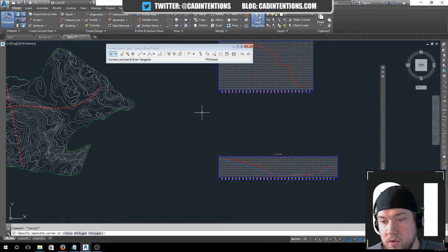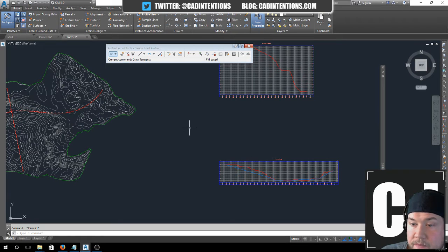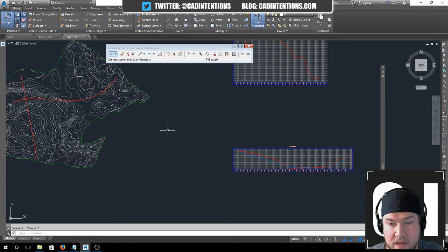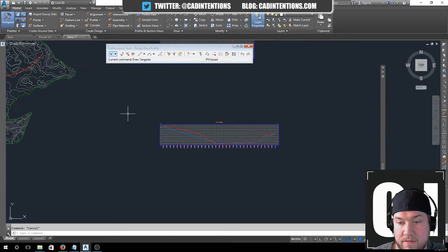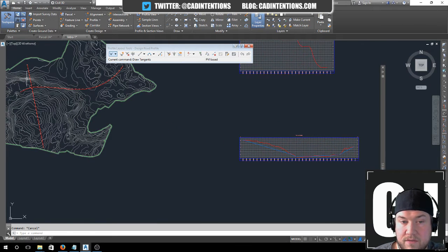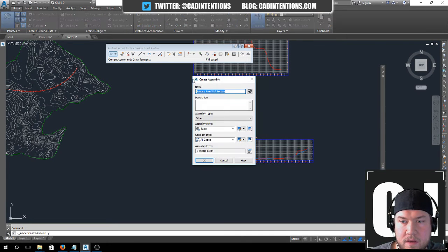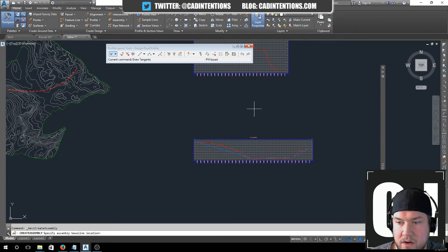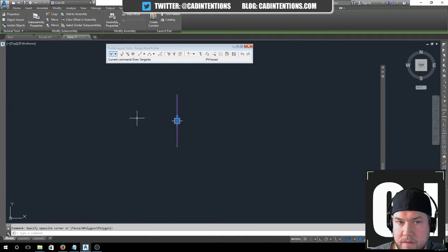Next up, in case you haven't used Civil 3D much, when you build a road corridor, you need an assembly to cut along this profile. It's going to take a pattern that we draw in cross section and cut it across our vertical profile over here, and it's going to follow this alignment. It'll make a little more sense once we make one. We'll just leave this as default, so we're going to create our own assembly over here, and it just gives us this little node here.